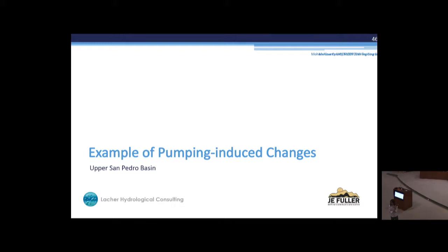The groundwater is groundwater, but unless you're producing from that saline zone, you're not going to stimulate an upward gradient. Unless you're producing right above it, you're not going to change anything. You're not going to induce mixing. But that is not something that MODFLOW can tell you.